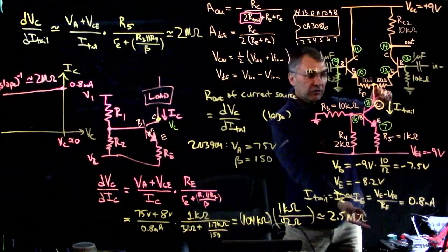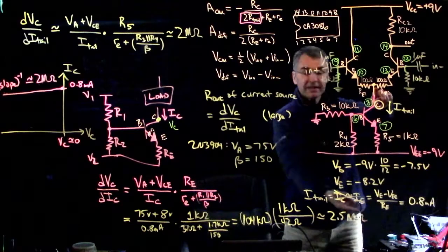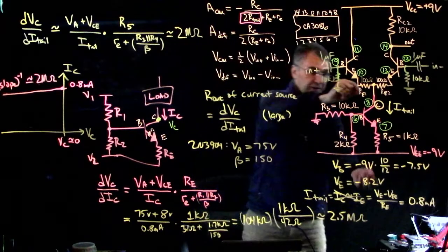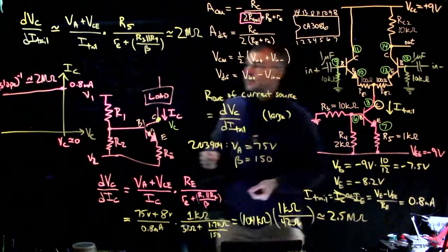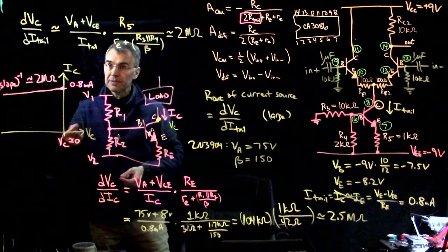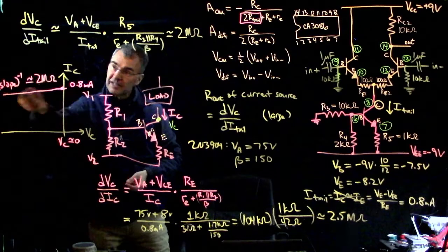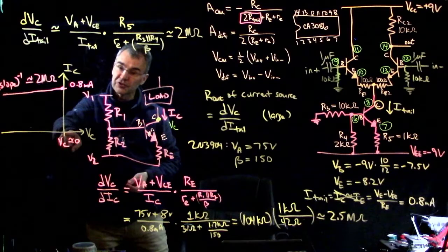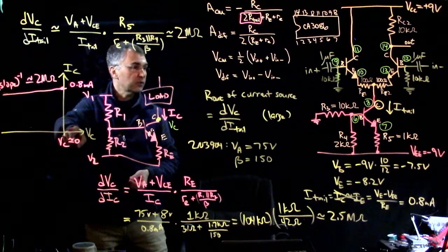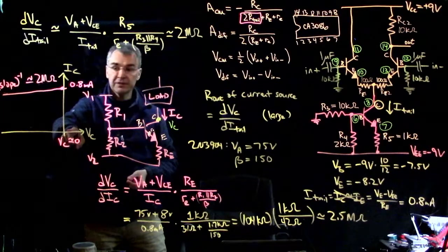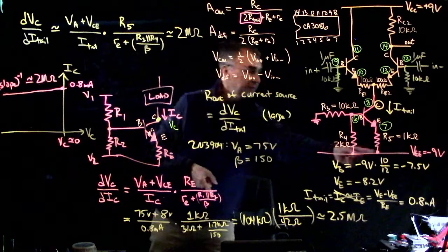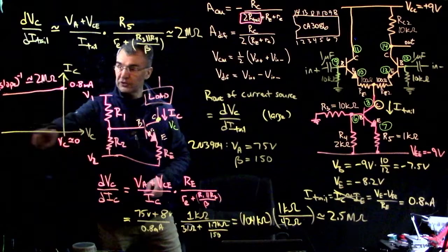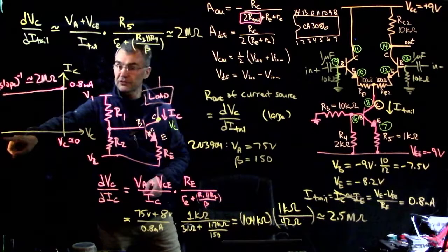You would need a 2,000 volt power supply to get that good an effective tail resistance if you were going to use a resistor. Because with a resistor, the IV curve goes through 0. When you have 0 current through the resistor, you have 0 voltage across the resistor.